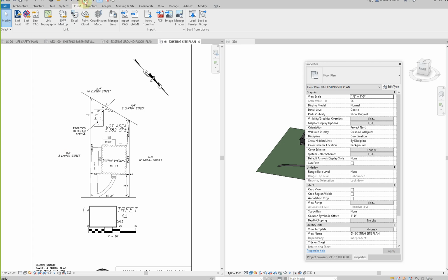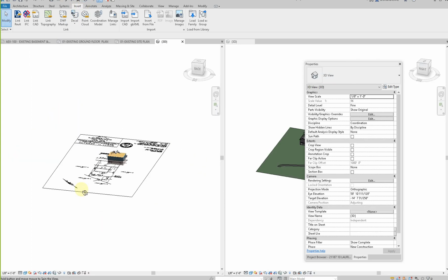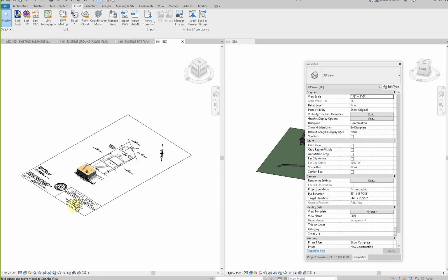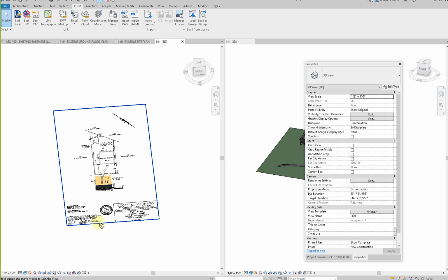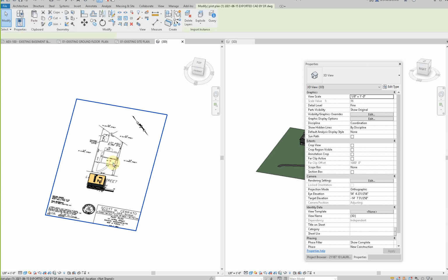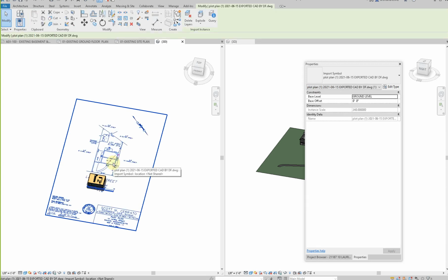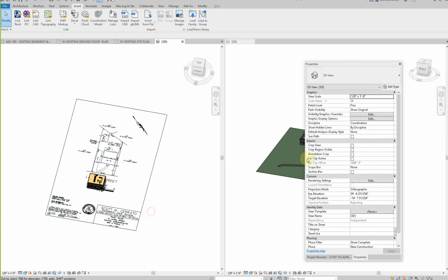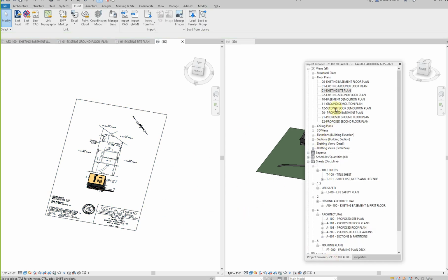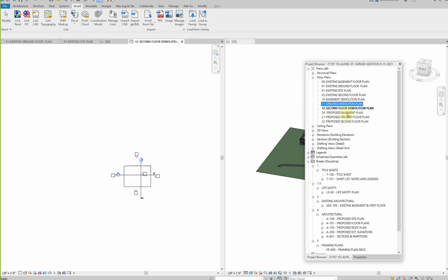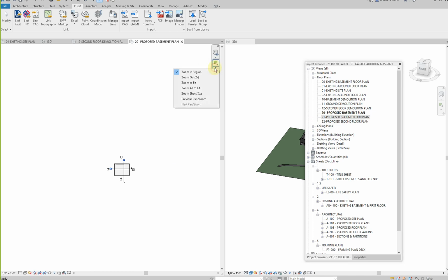Now, if you go to 3D view, it is there as a 3D element because we didn't say current view only. It brought us to 3D. I don't like to do that. That clutters the model a whole lot. It just gets very messy. I don't like messy stuff. Plus it starts showing up on every single view that you've ever done. Quite frankly, if I go to any view, this stuff is somewhere hanging in there. I'm telling you, it's not showing up, but I promise you it is somewhere in there.